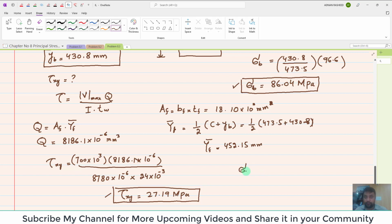Now you have normal stress as well as shearing stress. So you can put it in: sigma 1 is equal to sigma average plus R, and we know that sigma average here is only the normal stress sigma B divided by 2, plus R, which is the square root of sigma B divided by 2 whole square plus tau xy whole square.